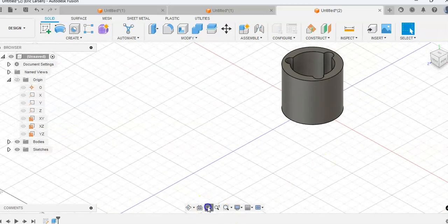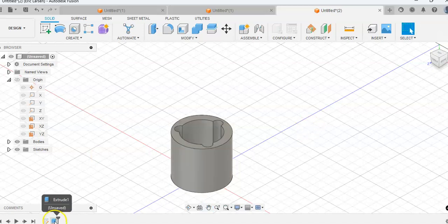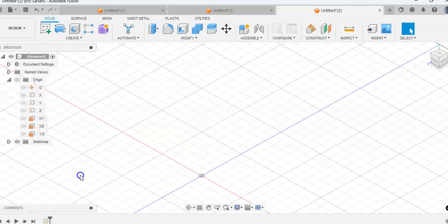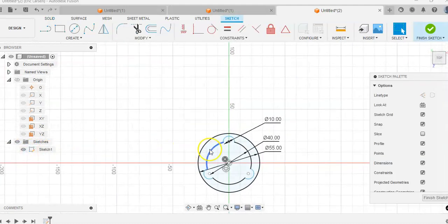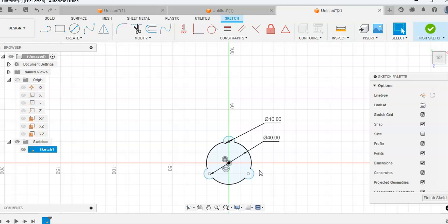Okay, there we go. Now you can see that this is pretty good, but it's something that will require a fair amount of filament in order to create, and it's actually thicker than what we really need. So what we will do is we will hit escape, go back down to the bottom and delete the extrusion, and now we'll hit the caret and turn on this sketch. Double click on it, we'll edit the sketch and select the outer rectangle and hit the delete key.